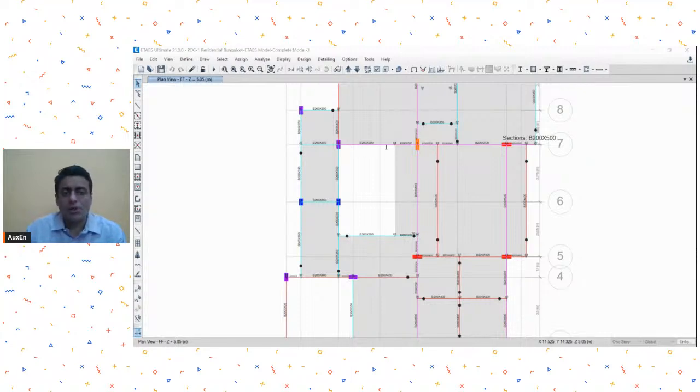So now this is a constant value. So just give it a constant value 0.06. Okay, and so at t equal to 0, time period equal to 0, the AV function will give you a value of 0.06. At any other time period, let's say time period equal to 10 seconds, also the AV function will have the same value, 0.06.